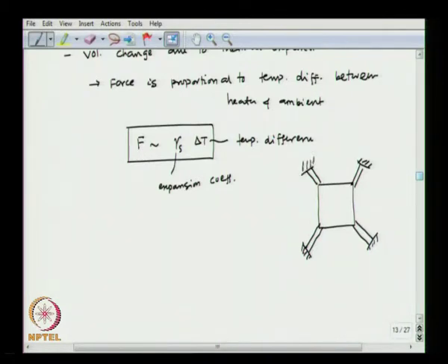So, the membrane is going to be hinged on 4 sides, and the heaters will be mounted on these structures. Initially this plate is going to be in contact with the valve inlet. So, the valve will be closed, and when the heat is supplied to these heaters, then there is a compressive stress that develops within these members, 4 members, and at some point the compressive stress exceeds a critical value, and then the valve pops out. Okay. So, the valve is open.